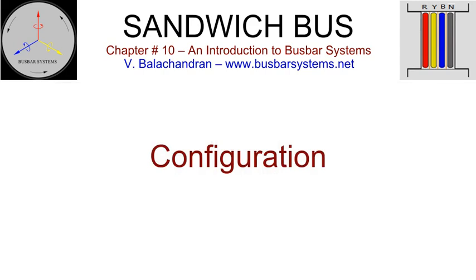Configuration. Busways are manufactured in several conductor configurations, 3 for triple pole to 6 for triple pole with 2 neutral and 1 earth, depending upon the system, and installed in 2 different conductor orientations, vertical and horizontal. It is the normal practice to have all the conductors of equal cross-sections. The neutral conductor size is the same as that of the phase conductor. Under certain circumstances, the neutral conductor size may be twice that of the phase conductors.